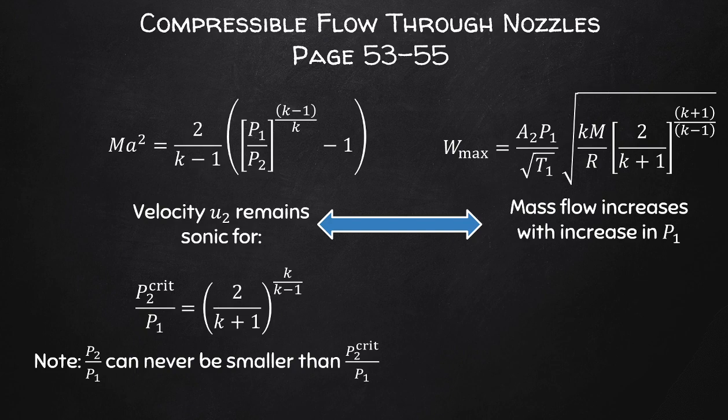The mass flow rate is a maximum and is still dependent on P1 and obviously T1 as well. So if we can measure all of these properties, or we know the properties of the fluid, then we'll be able to measure a flow rate through the nozzle, and obviously then back calculate the flow rate through the pipe diameter.